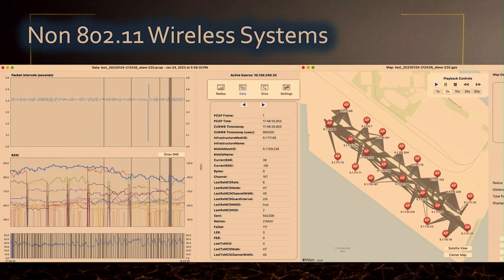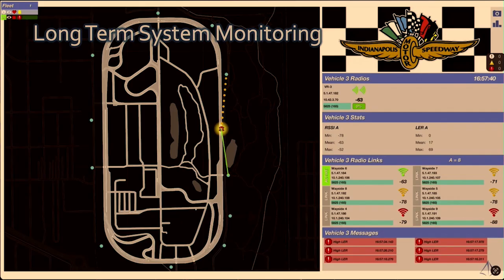Another thing you can do with these systems, if you're lucky enough to have outdoor and be able to get reliable GPS, this is a port job that we did, is use Apple Maps integration. You can import a CSV with your AP locations, and then step through packet by packet and see where that client radio is connecting, and follow it along. So then you can see, okay, am I handing off between a bunch of radios? Maybe I don't have a good antenna position here. This is really useful for being able to visualize that.